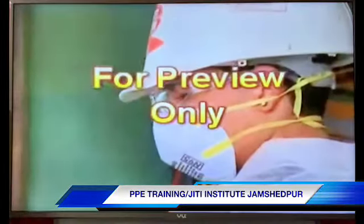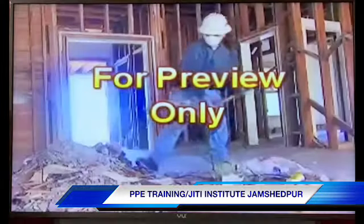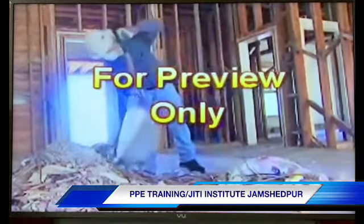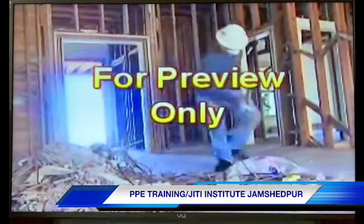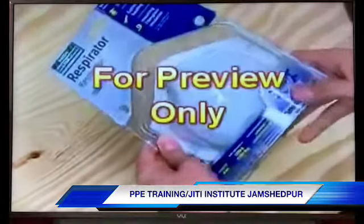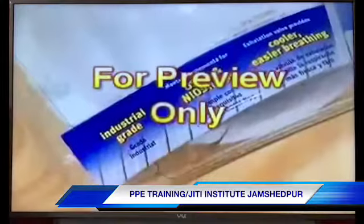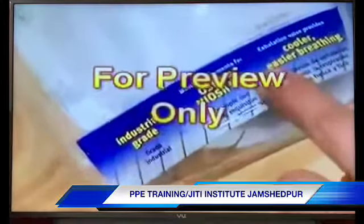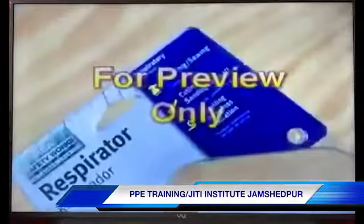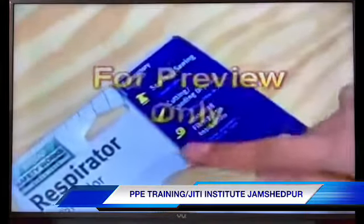A dust mask or filter face piece are negative pressure particulate respirators with a filter as an integral part of the face piece, or the entire face piece is composed of the filtering medium. These masks provide the least protection of any respirator and are the least sophisticated. Different masks have different degrees of filtering capabilities. The instructions on the mask will tell how efficient the mask is.